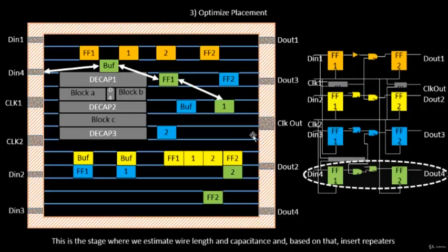Okay, next you have this connection from this point to this point. Again, if you see, the distance is a bit high, and also there is a logic sitting over here, and this again is a normal condition. The way the routing might happen is that the internal routes of flip-flop 2 might be in some layer, let's say metal 1, metal 2, and the signal connection from 1 to 2 will be on a separate layer, like metal 3 or something of that sort.